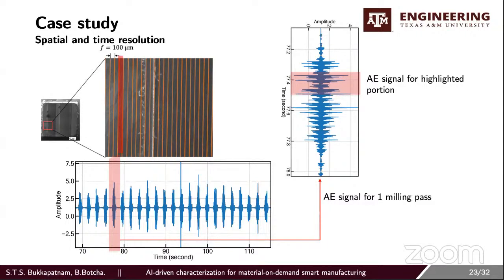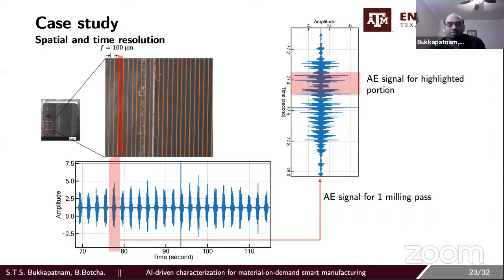These are great questions, actually. Let me quickly answer. Bhaskar, I would like you to think through that too. First question is, how will it behave when you have a very high finish on your surfaces? It would not go left or right, but the energy will actually come down. In fact, acoustic emission is perhaps the only kind of sensor that has the sensitivity to indicate some changes in the micro machining regime in those fine finish cut ranges.